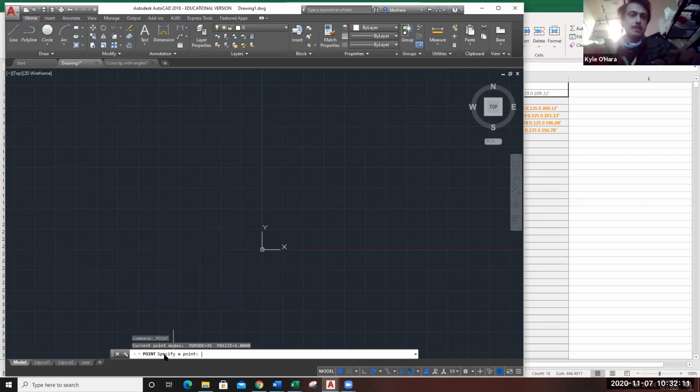Well, how do I specify a horizontal distance and an angular measurement in AutoCAD? Well, I specify the distance, say 120. And what is the horizontal angle? The way that AutoCAD accepts that information is that you use the less than sign, which indicates an angular measurement.